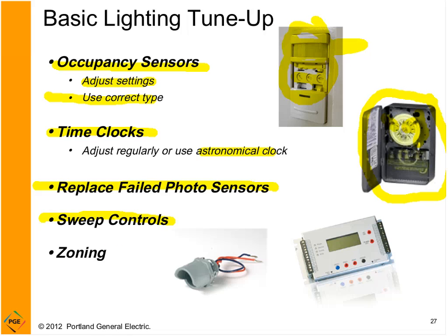And then finally, zoning. Whenever you're working with, especially an older facility, occupant needs change over time. Walls have to move sometimes to fit new requirements. And so when you move a wall, make sure you move the wall switch that is controlling the lights in the area. The last thing you want to do is have a light switch in a closet that's controlling most of the facility. If it's out of sight, it's going to be out of mind, and lights are going to be left on more often than they're needed to be on.